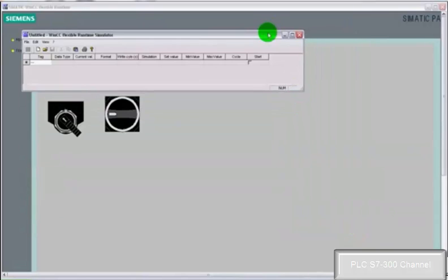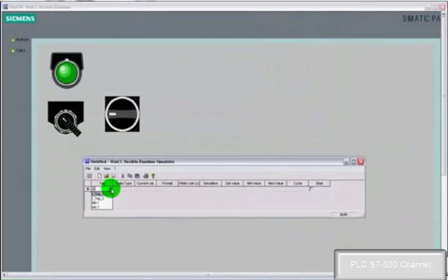we can drag that down a little bit, select our tag 2, but this time we want to put an integer value in it. The value is defaulted at 0 at the moment, so you see the graphic as you see it now. If I put a 1 into it, the switch moves to the second position. If I put a 2 in it, it goes to the 3rd position. If I put a 0 back into it, the switch effectively goes back to its first position.